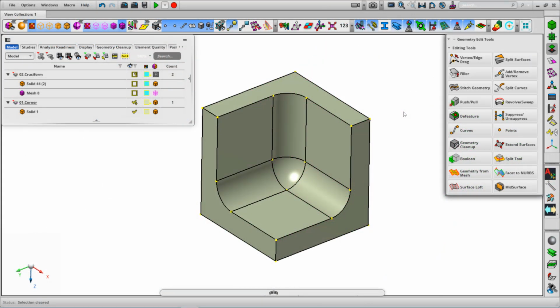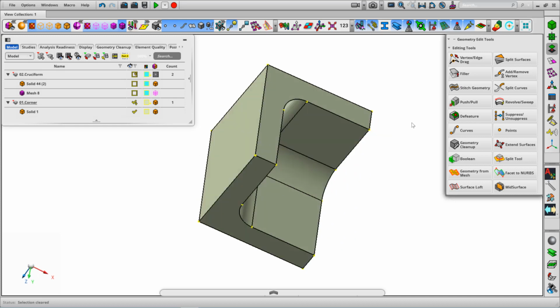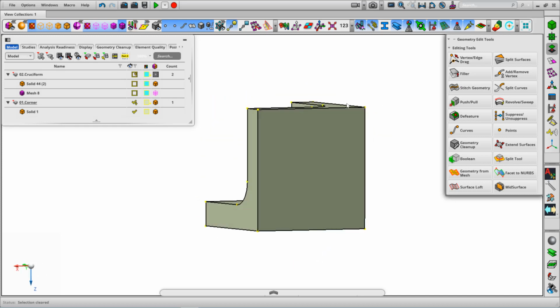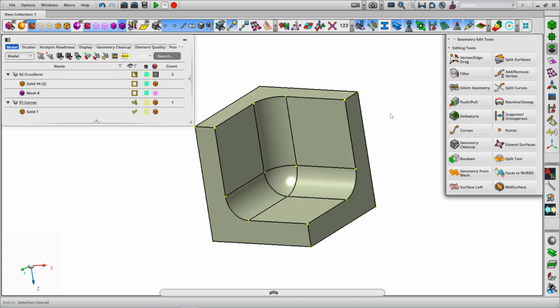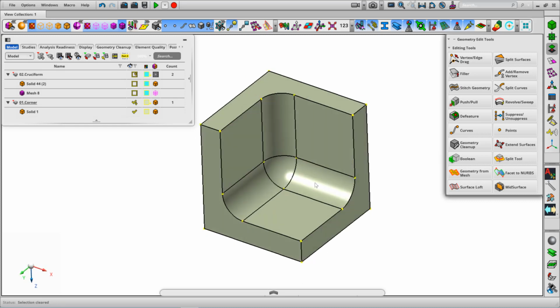Okay, so we're going to look at a quick example showing how to hex mesh a compound fillet. This is a piece of geometry that's been generated that's representative of a compound fillet. That's a fillet where you've got fillet surfaces meeting at an intersection point, and traditionally this has been difficult to deal with from a hex mesh perspective.